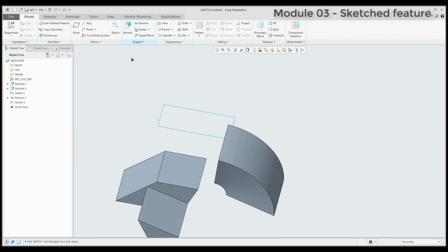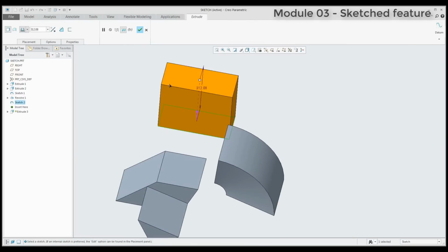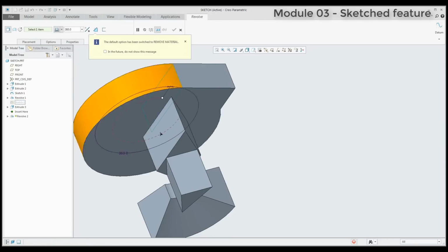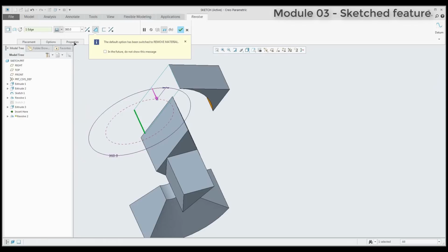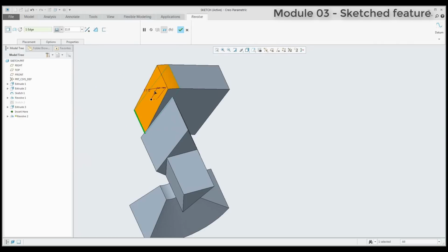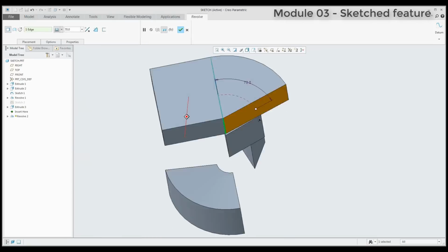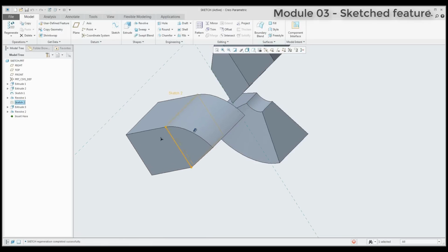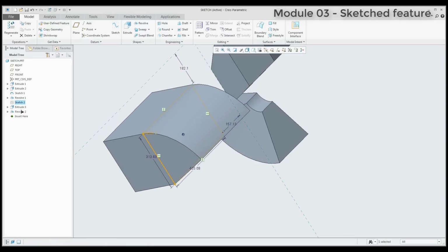And you can use this sketch, for example, for the extrude feature, or on the opposite way, I can use that sketch for the Revolve feature, and this is my axis of revolution. We can switch off or switch on if you would like to add material or delete material. You can see right now that I use the one sketch, and if I edit that sketch, the system will change the extrude feature and Revolve feature for me.